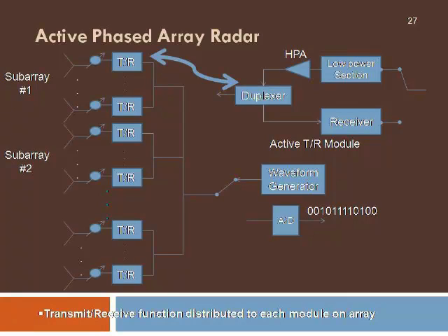We'll have separate transmit and receive sections. The low power section will be directly getting the signal from the base, and after this it's going to be amplified. Then via a duplexer, the transmitter signal is connected to the antenna. The received signal from the antenna is going to be directed towards the receiver by the duplexer. The receiver will do some sort of pre-processing and then direct the signal back to the ground station.